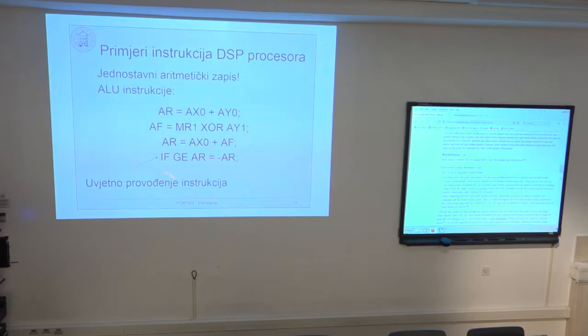And this means that if condition is satisfied, the instruction is executed. If not, it simply is no operation. So nothing is executed. Only one wait state, I would say. And do you know why would this kind of approach be much better than really branching? What is the advantage of using this kind of assembly level conditional execution?